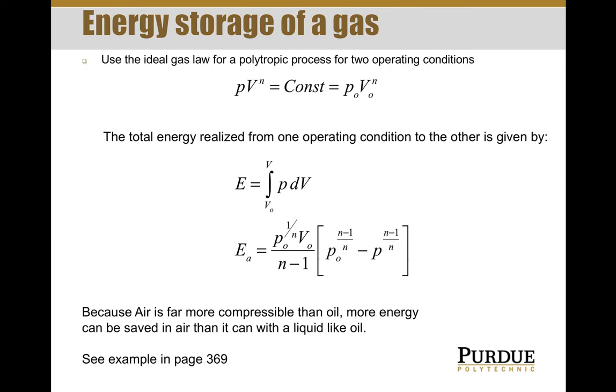It's not compressible. But if you have air in a vessel and you put a piston to it, it will compress and it will minimize that volume until it can compress no longer. But as soon as you remove the force of that piston, it will recover its original shape and it will tend to occupy the maximum volume available. And so by virtue of that compressibility, you can say that you can store energy in the form of potential energy. And so we have here an equation that tells us what the energy of the compressed air is.